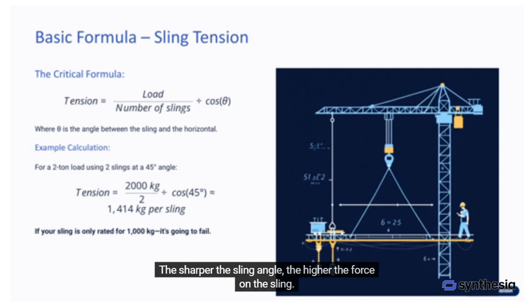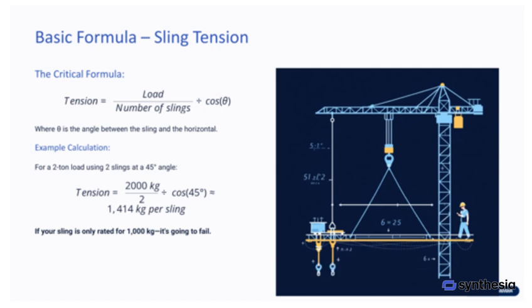Key takeaways. The sharper the sling angle, the higher the force on the sling. Always ensure your slings can handle the calculated tension to avoid equipment failure.